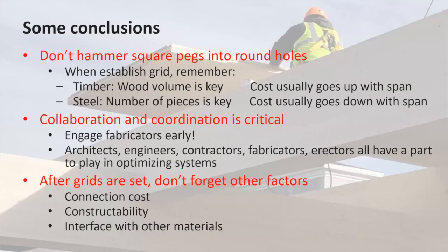Quick conclusions: don't hammer square pegs into round holes. Timber is timber and steel is steel. Collaboration and coordination early is really critical. Engage fabricators early. And then after grids are set, don't forget other factors: connection costs, constructability, and interface with other materials.